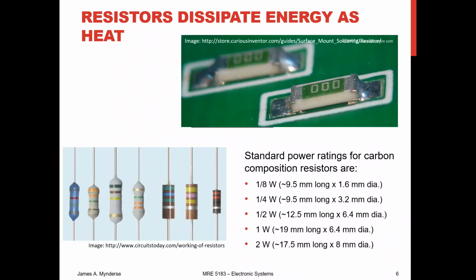I do not have any 1 or 2 watt resistors in the lab. Those are relatively large physically, and I tend to think of those as also being lower resistance values. If you need something that big, be careful, don't use something smaller. You can always calculate your anticipated power dissipation, and if you know it, it helps you choose